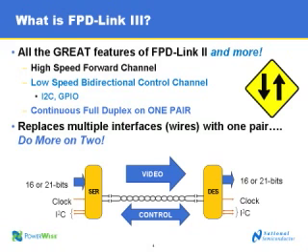The diagram here is showing a simple explanation of what's going on. We have 16 or 21 bits of video data being transmitted in the forward direction, and then the deserializer takes that and sends it to a controller or a display device. And at the same time, we're sending control data backward and forward between the serializer and deserializer. This is the I2C and the GPIO data.